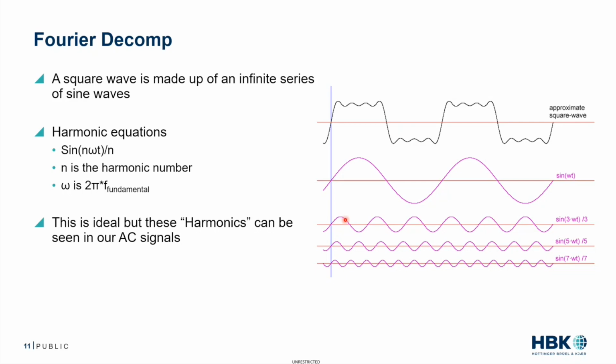Because if one instrument has a 3 kilohertz filter and one has a 30 kilohertz filter, you're going to see different values, because these harmonics have their own phase distortion. They have their own reactive element. They have their own RMS element that's getting added into the total. That gets even worse when we look at switching. And again, we'll get there.